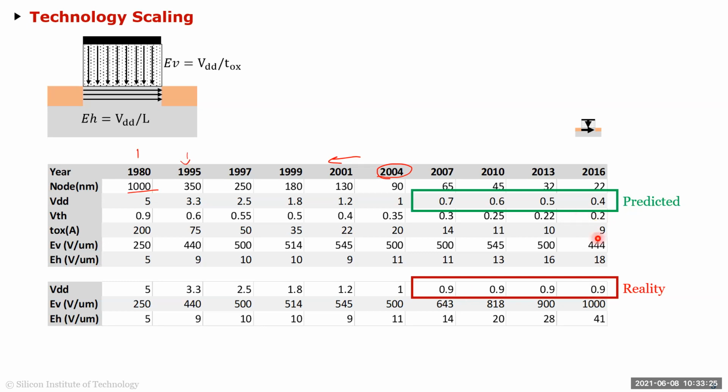If you want higher VT, then obviously you want excess gate voltage to drive higher currents, because people want faster devices, smaller devices, and they're all resulting in these conflicting parameters. And so the balance has been, the supply voltage is staying at around 0.9 to 1 volt, the threshold voltage around 0.3 to 0.4 volts, which has resulted in these higher fields.